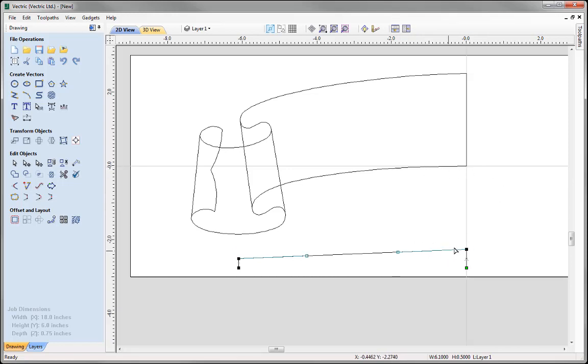And we're going to do the same here. So I'm going to take this node here, hold down shift and select this node here, then I'm going to press Y on the keyboard to align that shape in Y. Right then, so now I can take this node here and bring that over a little bit, so you can see we've got this curvature coming round and then it's coming down at this point here. And this cross section represents this fold here.